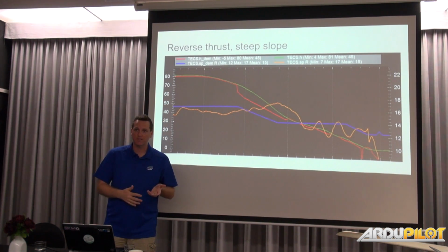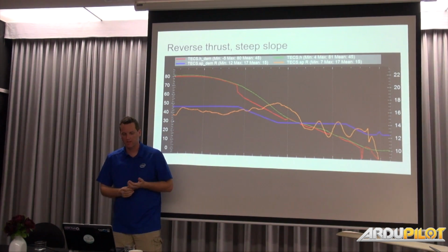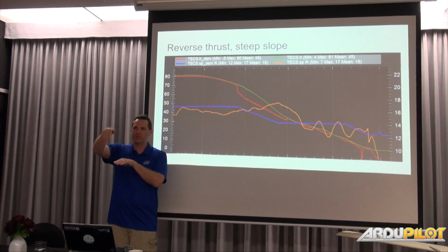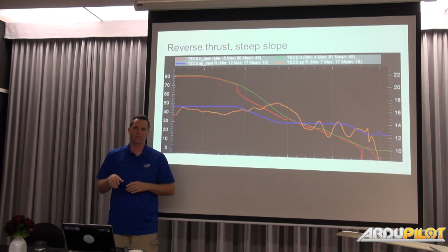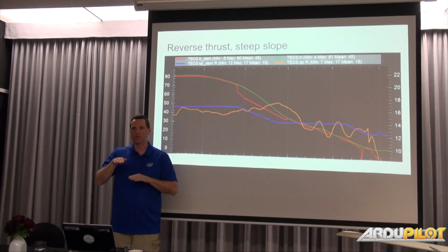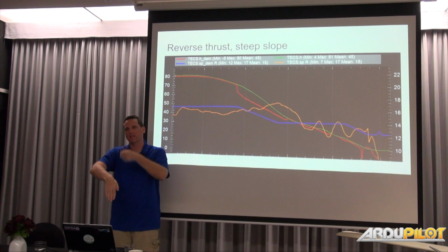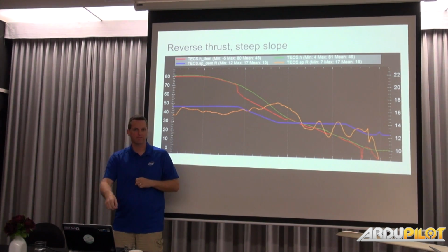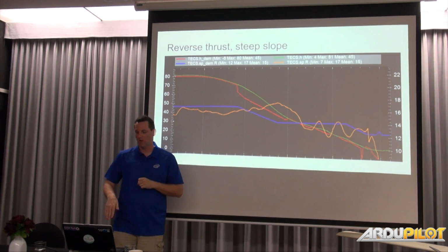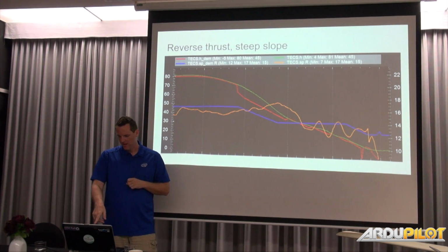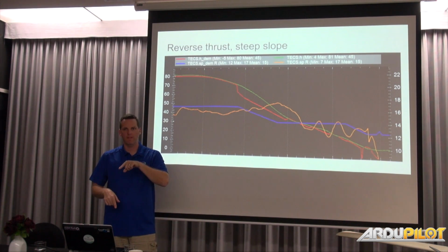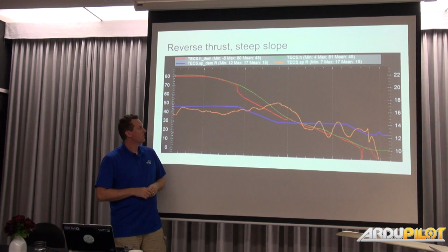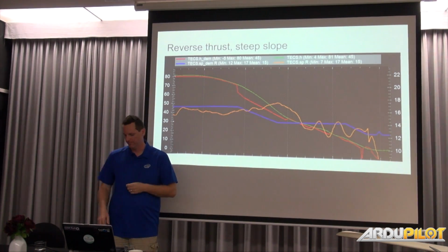And then for reverse thrust, your demand would just drop down and you're terribly overshooting and just slam on the reverse for the thrust to really get down there. So at first you speed up a little bit as it tips down, and then you're throttling up, or throttling negative, and then it catches up, and it's hunting to get your airspeed down low, but it gets down much lower that way. And then you see the second jump, right here, where it's hitting the pre-flare.